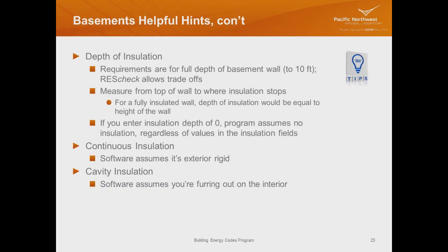Some other helpful hints here is continuous insulation. So the software will assume you have exterior rigid foam board. When you enter a continuous R value into the software, it has to make an assumption. Cavity insulation is assuming that you have insulation in between structural members.